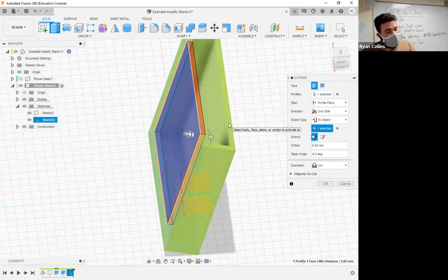But now if I went back in the history and changed that original sketch to that offset of, all right, you know what, I decided I want that like 2 millimeters wide because it's too thick and it's using up too much material. This extrusion here will automatically switch to 2 as well, because it is dependent on the thickness of the wall. So you just start getting things that stack on dependency, and effectively it all becomes relative to whatever previous dimensions were.